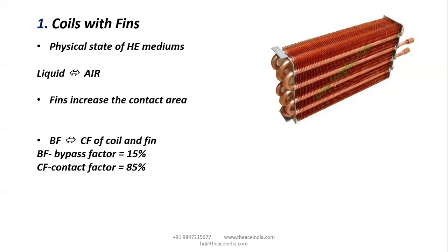Typically, the concept of the evaporator and condenser are the same. That's what I told you. Both are termed heat exchangers. In the case of the condenser, the hot air should be rejected to the atmosphere. Initially the atmospheric air should contact the coil with fins, and thereby a small heat exchange is initiated between them. Then due to the high temperature inside the coil, most of the heat is absorbed by the atmospheric air and rejected to the atmosphere itself.